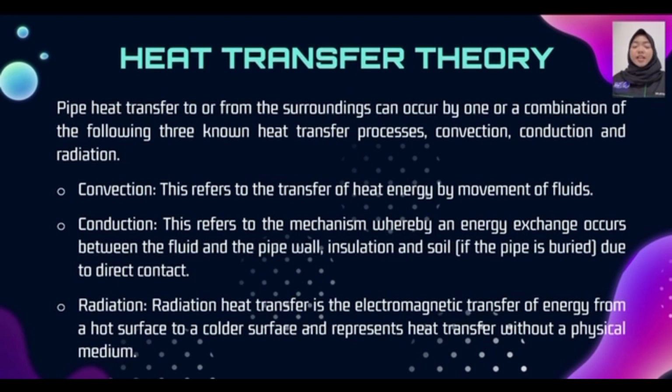Convection. This refers to the transfer of heat energy by movement of the fluids. Number two, conduction. This refers to the mechanism whereby the energy exchange occurs between the fluid and the pipe wall, insulation, and soil if the pipe is buried, due to direct contact. Lastly, radiation. Radiation heat transfer is the electromagnetic transfer of energy from a hot surface to a colder surface and represents heat transfer without a physical medium.